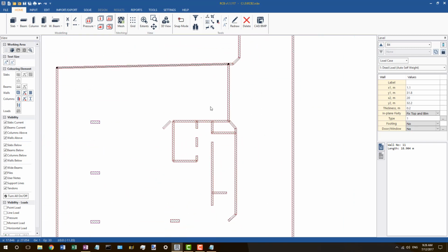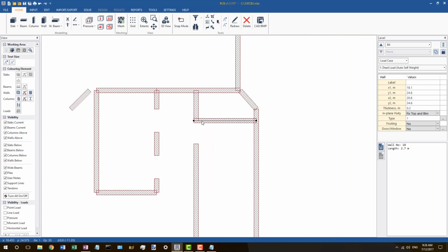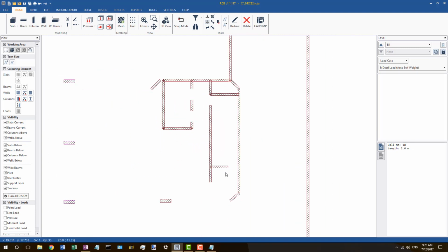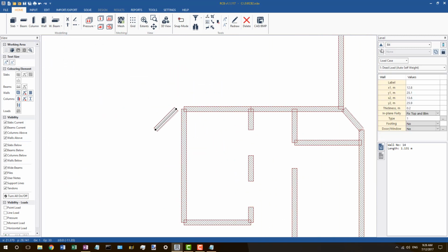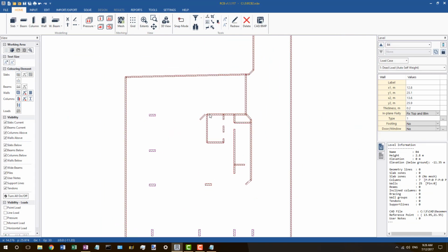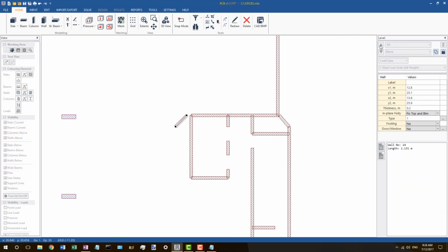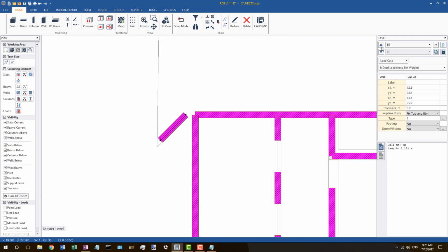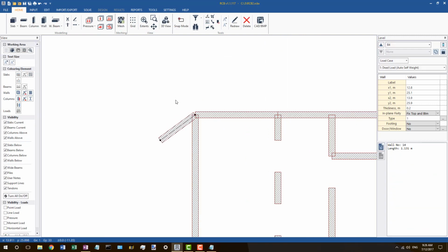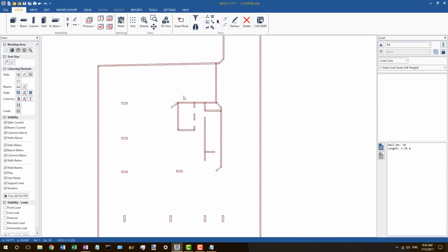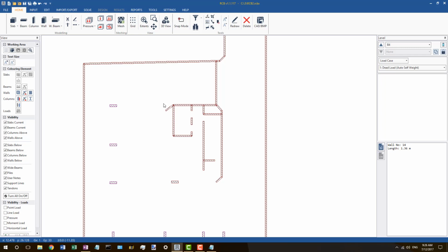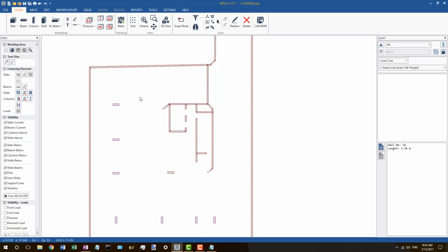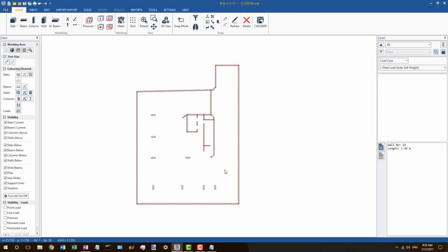Now let's go through and have a quick visual inspection of these other walls. So just pulling these walls back to the center lines. These should be touching on the center lines. Now let's see what's going on here. This wall, we can keep it as it is. For simplicity, let's just pull it to the corner here. So again, sacrificing the true accuracy to basically get the model running smoothly. Again, at the end of the day, it's not going to affect our results in a big way. So basically, this is the basement 4 floor done.